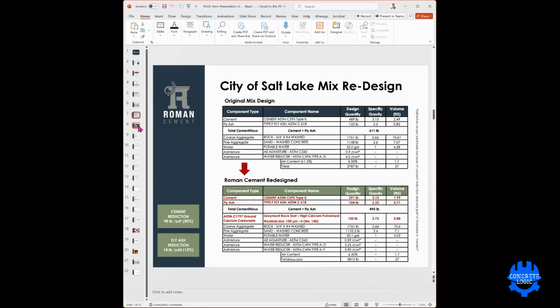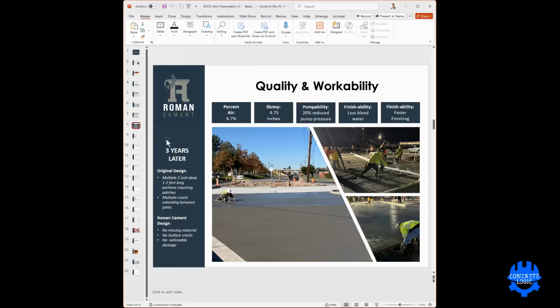Okay, so you're proposing just a whole different SCM, is my understanding. Yeah, I guess you could say it's an SCM microaggregate. Here's just a photograph. Have you tried presenting it in that way? Is that how you presented it to the DOT? Yeah, we presented it to the DOT as something that qualifies under ASTM and ACI standards, but it doesn't qualify as an SCM per se yet. Like I said, it's defined in 211 as a mineral filler. It's not counted as an SCM or cement.